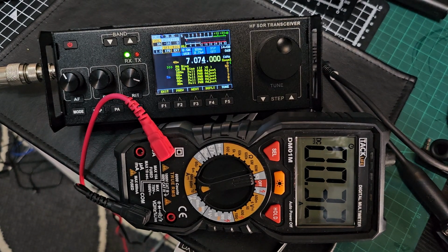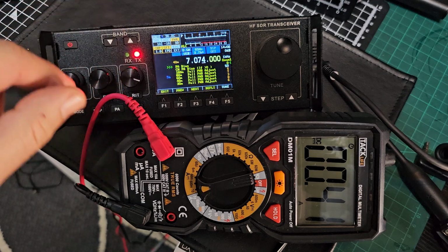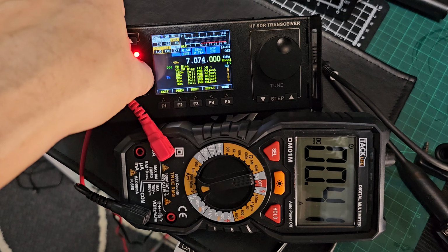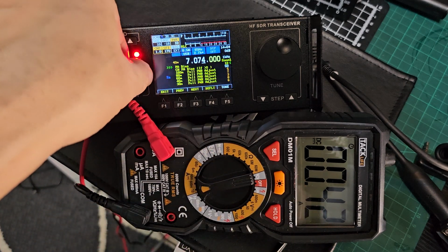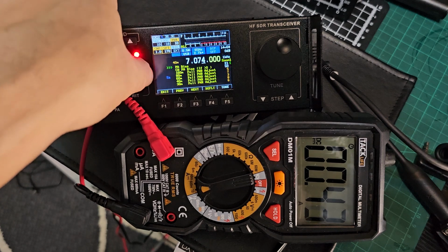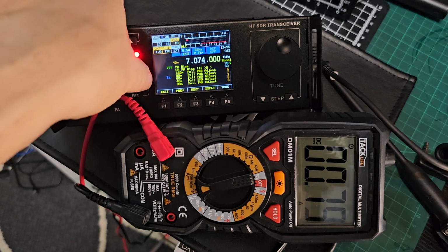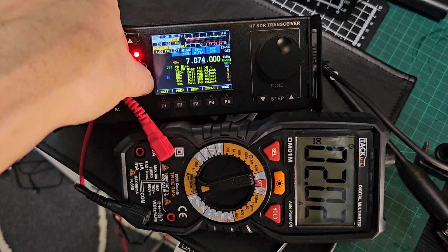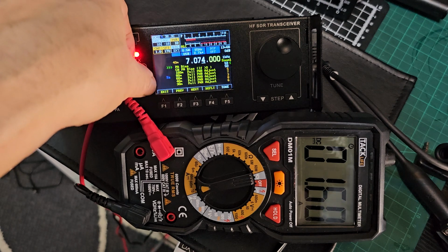So we'll key my microphone, and we're going to increase the RIT until this says 91. So it's the PA bias, we're turning it up, and this will start to go up. Because it was 41 on 0, we want it 500 higher. So we want it to say 91, and we're turning the PA bias. You can see it's gone white. Like so. We've gone too high there. Let's go back down a bit.